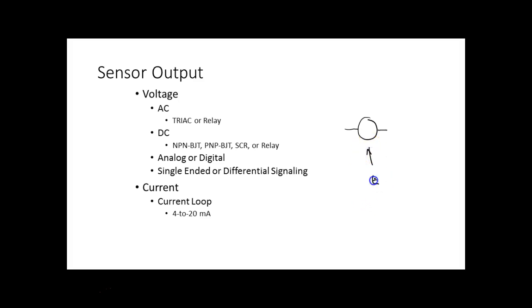First of all, we have a what? An electromagnet, and that's what we call a coil, right? So it generates a magnetic field when we put a voltage across the coil. And what do we do with that electromagnet? We use it to open or close contacts, right? That makes sense. So that's all it is. That's all a relay is, an electromagnet.